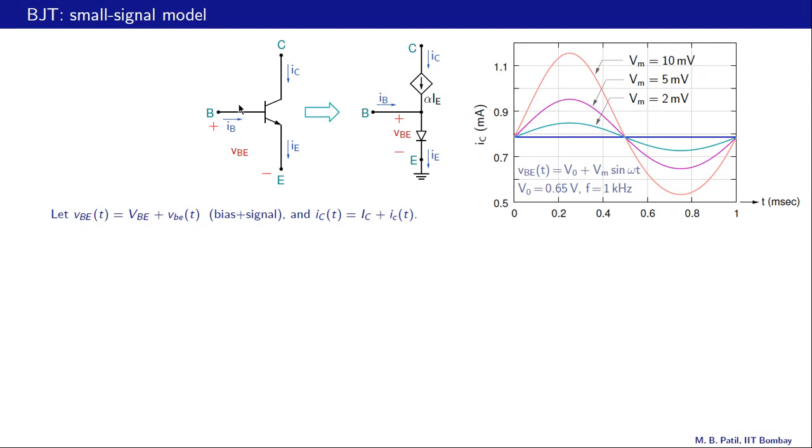The exact value of the reverse bias of course is not important. Now in these conditions, that is in active mode or in the linear region, the device model, as we have seen before, is given here: the base emitter diode and then the current controlled current source. If this is IE, that is alpha times IE. So we are of course very familiar with this model by now.